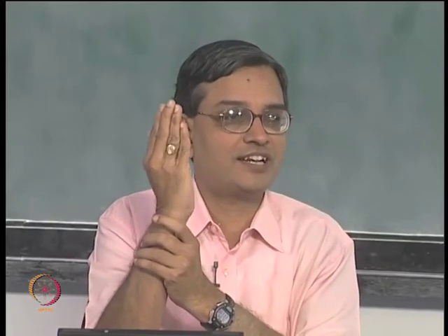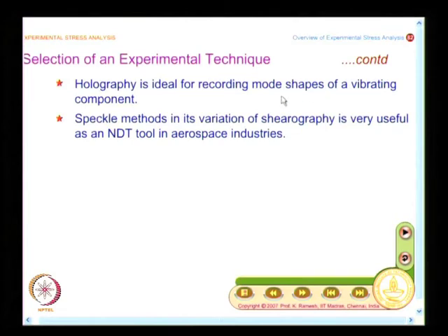Suppose I want to do it for a turbine blade, which has a complex aerofoil shape and is also twisted. That is where holography came to the rescue, because it is essentially an out of plane measurement technique. It found interesting application in finding out the mode shapes of a vibrating component.